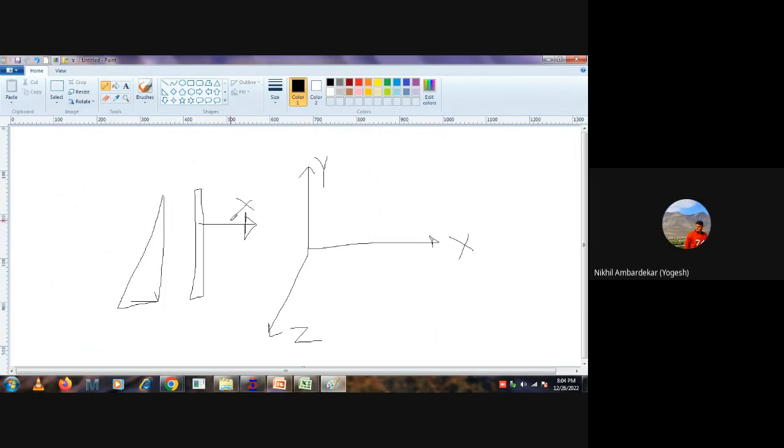Let's say, or maybe what I will do, this is Z. This can also happen, correct? So this is Z. We need to apply the local Z. So this is local Z, but STAAD wants to know. Apply local Z, that is fine, but STAAD wants the other direction also. So that's why it is asking about global axis, interpolate. So with reference to this vertical, we are applying the horizontal as a local Z. That's why it is asking.